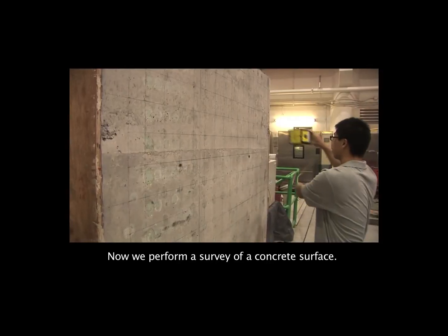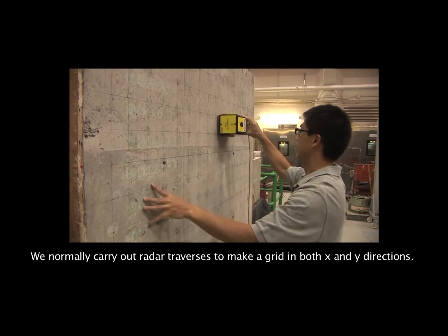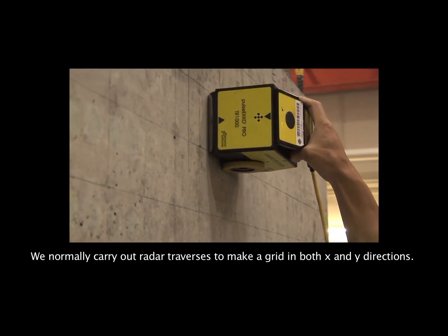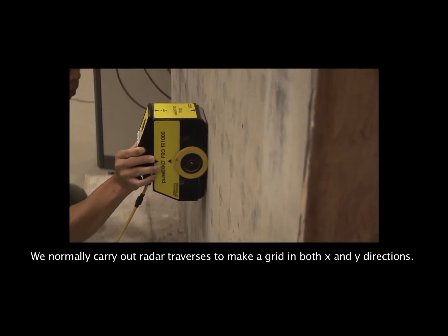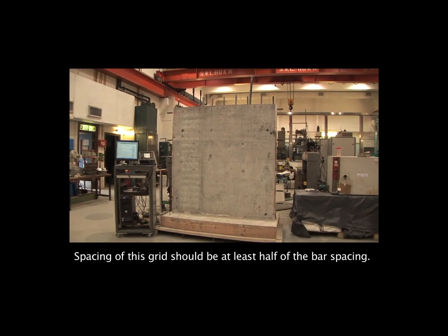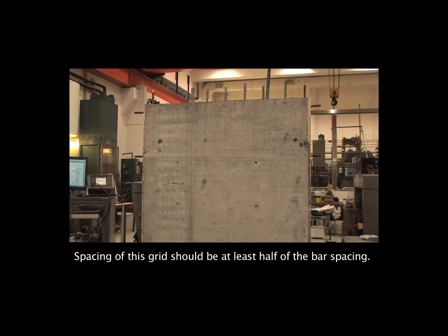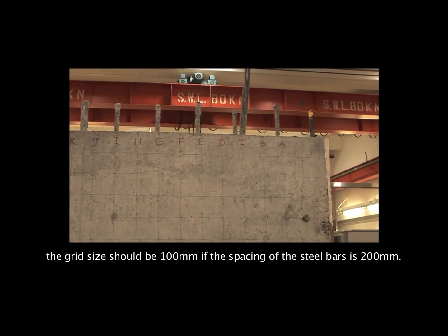Now we perform a survey of a concrete surface. We normally carry out radar traverses to make a grid in both X and Y directions. Spacing of this grid should be at least half of the bar spacing. For example, the grid size should be 100 mm if the spacing of the steel bars is 200 mm.